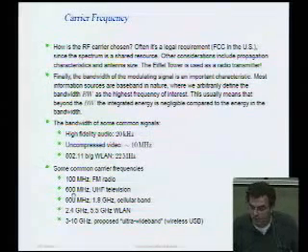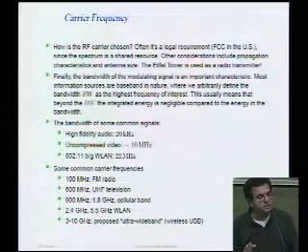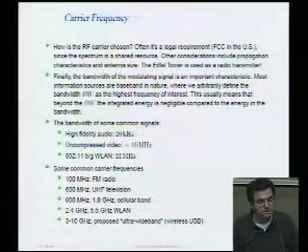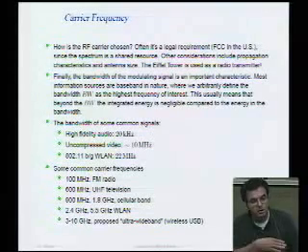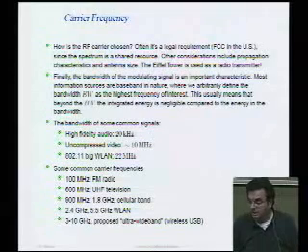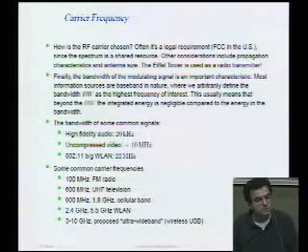And the reason is that UHF is probably one of the sweet spots in the spectrum, in the sense that you can get very good long-range transmission with reasonable antenna sizes. It's very good at bending corners and going through trees and walls and whatnot. And frequency is still low enough that you can build very low power circuits. So it's almost like an optimal frequency for building, let's say, wireless internet.